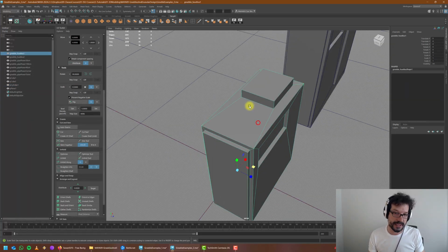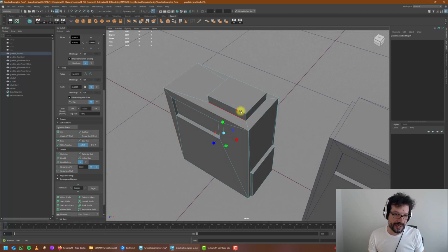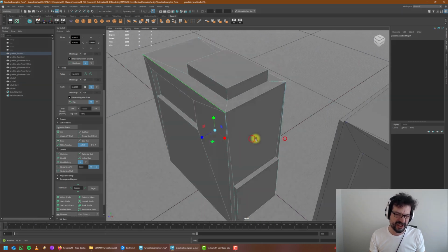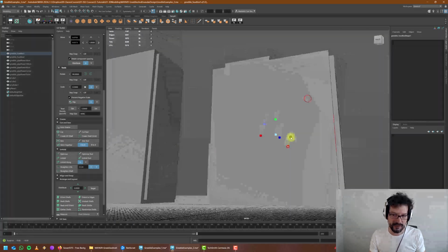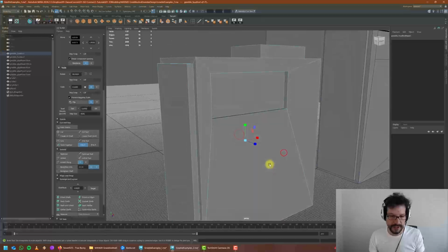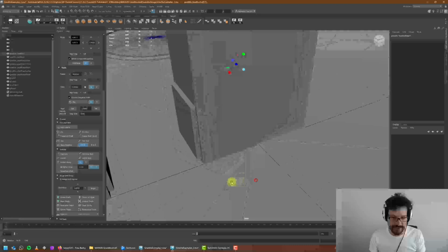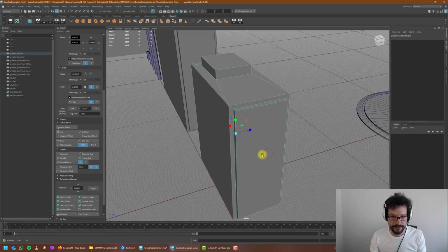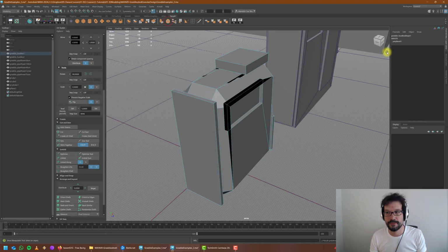Okay, you can easily go into any number of edges. And you don't have to do every single one of them. Like there's no reason to bevel this, but maybe only bevel these corners. Okay, only bevel the corners of the edges of the larger objects or the larger geometries. This is always a choice. These are all your geometric choices. Okay, and this one as well. Apparently, hopefully that's everything. Okay, let's go bevel them.